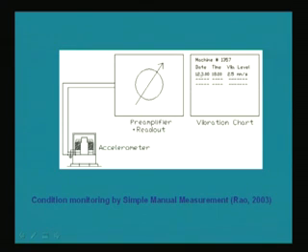And manually, if we want to find out the condition of the machine, maybe every day we can record this with time and details, and these charts can be prepared which will help us in the diagnosis of the machine fault. These are the conventional ways of doing it, in which we are just using the raw data, just bothered about the RMS or the peak to peak value of the vibration, and we are recording that.